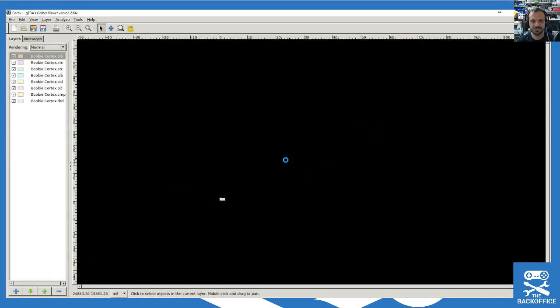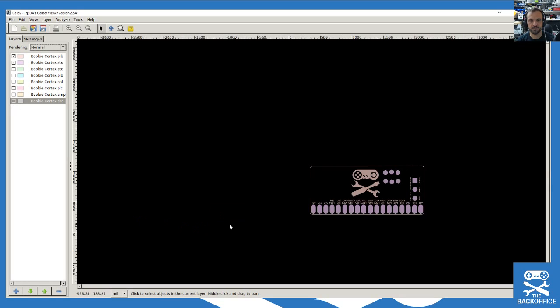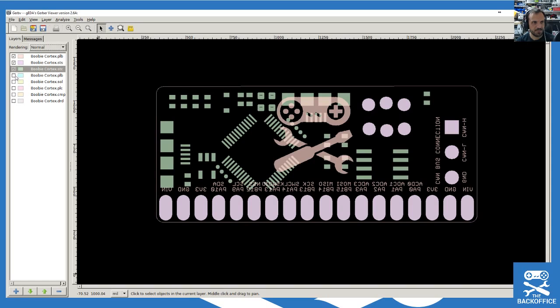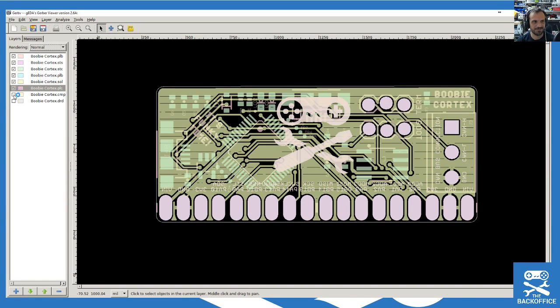Oh, yeah, by the way, look at that drill file. Do you see these holes here? I think that's the drill layer. I'm definitely a bit suspicious of that. The DRD layer looks way out of scale. So I'm going to have to look at that at some point. So yeah, you can see why you might want to pay money to PCB Pool, because they'll just take your Eagle file and deal with it. They've obviously built automation for that.